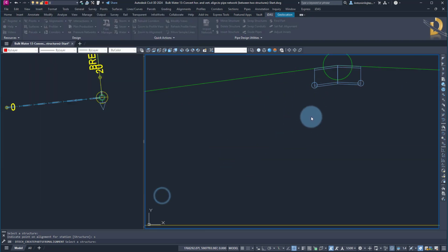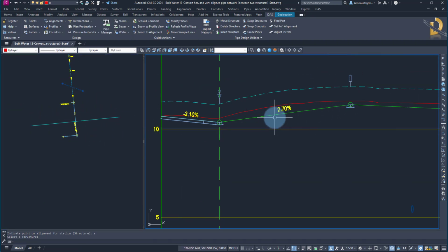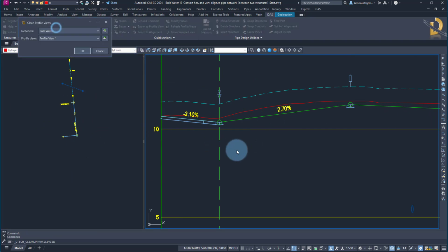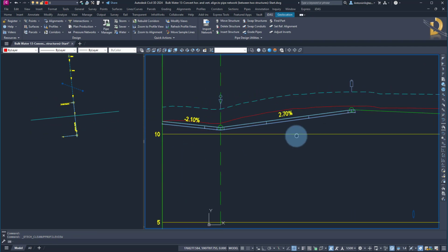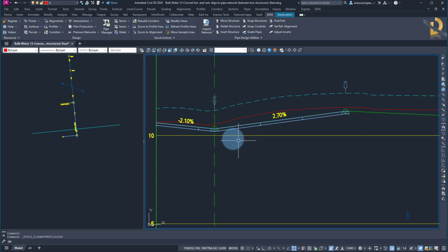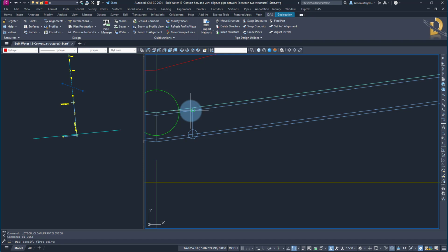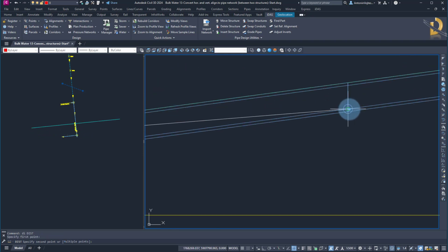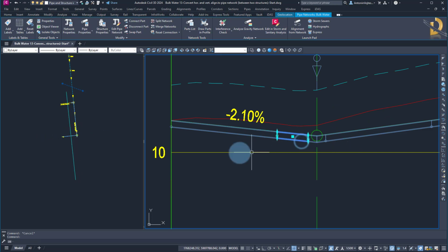Then I click OK. And again, those parts are created in plan. We are planning to automatically project those pipes to profile view. That's on our to-do list, but currently you need to run this command every time. And it creates another portion. And I specify the maximum distance or length to be 12 meters. So if I measure this length, which is of course horizontal projection, the delta X must be 12 meters, which it is exactly. So that's how it is designed. So I have pipes every 12 meters and then I have a remaining part. Like here you have a remaining part.